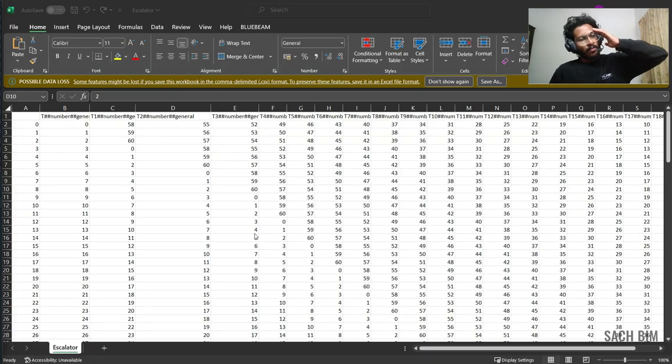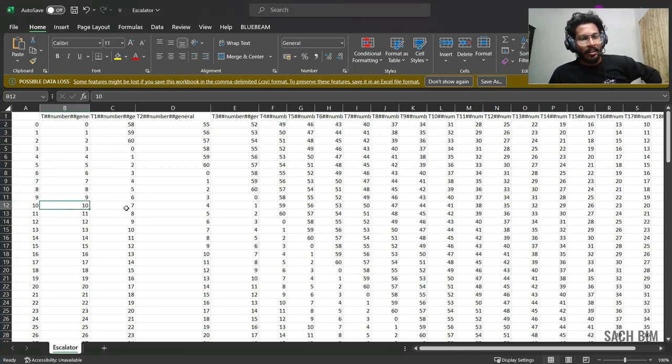For example, if T is equal to 10, then T1 will be 7, that means 10 minus 3, and T2 will be 4 and T3 will be 1, something like that. It is totally based upon the height of the stair. So for extracting this Excel into the family I'm using lookup table equations. I will show you that also.